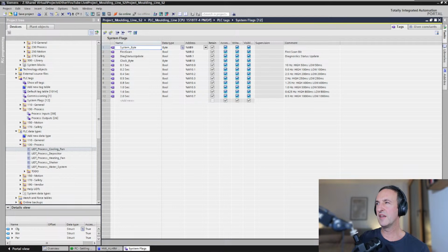Yeah, that's maybe a different way of doing it, Eric. I would normally not map inputs and outputs. If you would do mapping of inputs and outputs, that's good if you want to manipulate them. For example, if you want to be able to force inputs or force output states, which can be a good thing during testing of the line before commissioning, testing at the machine builder. I know some customers of mine have done that before, where you have an interface between the input and the actual inputs that you use in the software. That would be through some kind of manipulation, through a forcing or something.